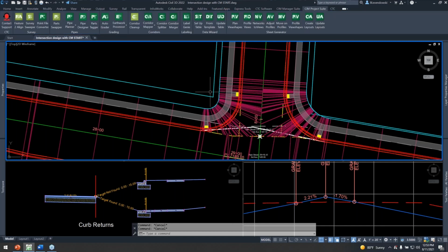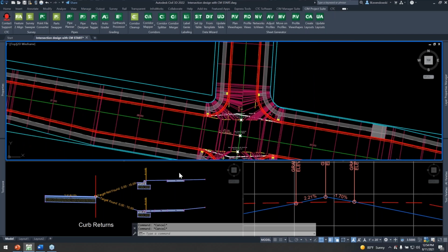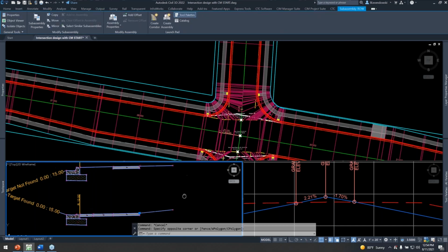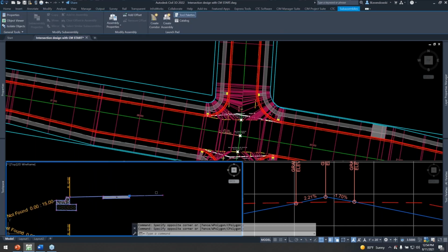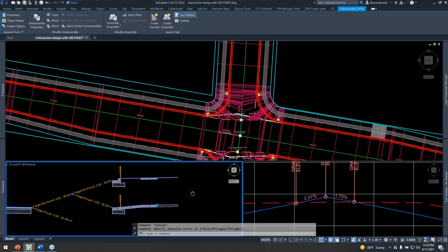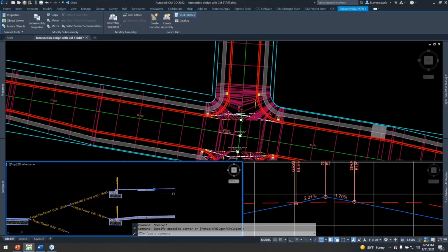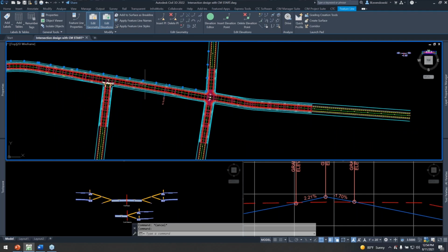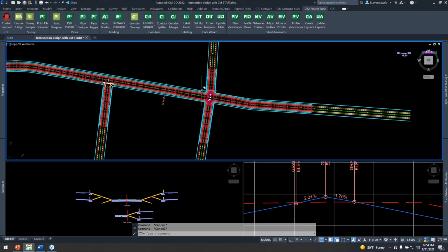And so we need to target those feature lines both for elevation as well as width with this back boulevard subassembly, as well as the back of driveway, the back of boulevard, and the through roads as well. So we've got a series of feature lines wrapping around the site here. Now these could be alignments with surface profiles, you name it.